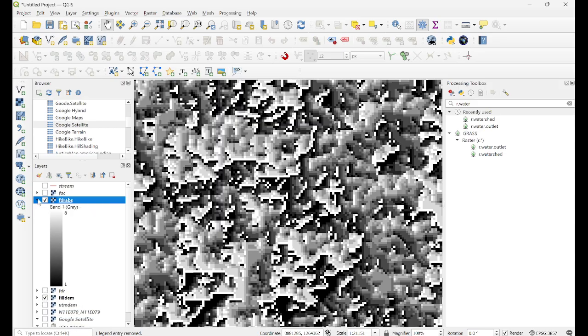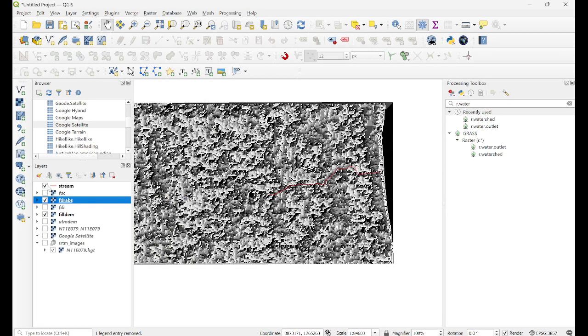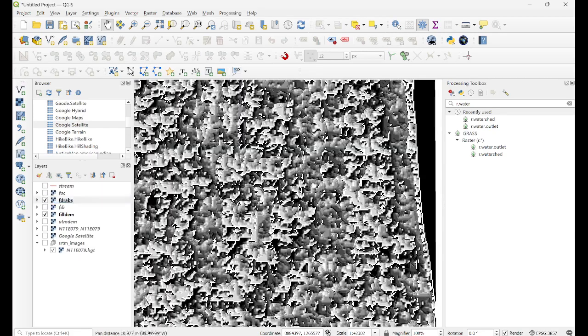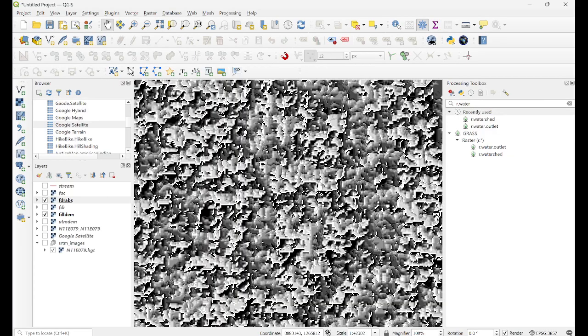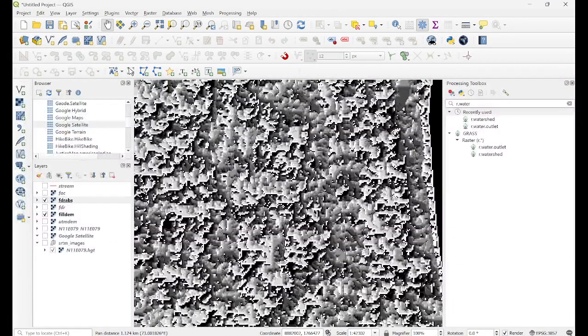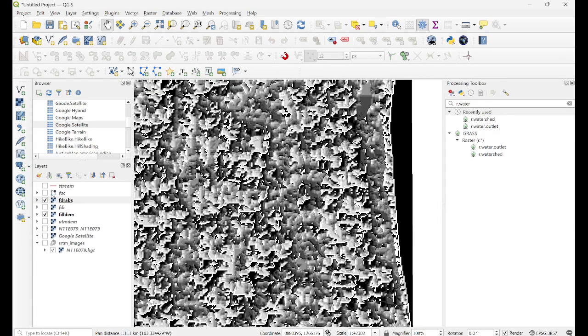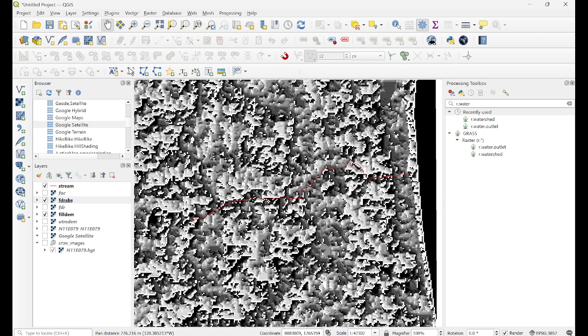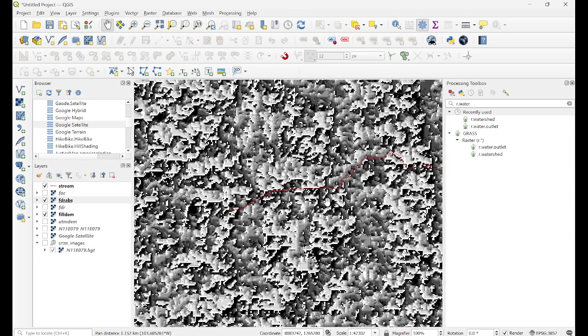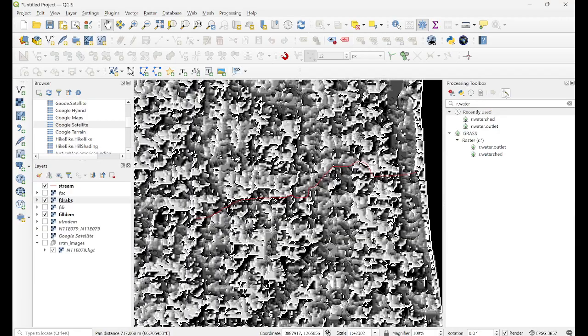So if you put this one, here there is no clear sign. Here you can see the better flow direction, but here the system is different, the direction is different, right? But our river flows like this. This may happen, but it will not help you, because if you delineate the catchment at this point where my cursor is, then your catchment will be like this, on the downward side, and it should be on the upward side. It may happen, but you need to know the process, right?